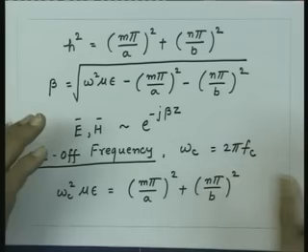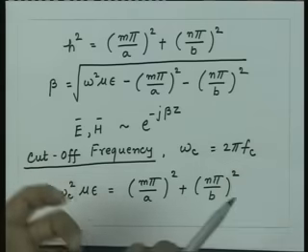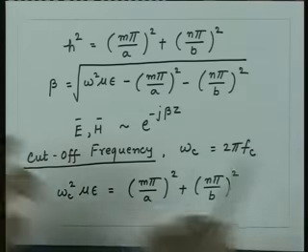Now if you want to send information on this waveguide, we will put the energy inside this waveguiding structure, and if a large number of modes can be supported, if the waveguide does not have single mode operation, the energy will get distributed into various modes, that means various combinations of m and n. Each mode will have its own velocity for travelling. So as they travel, the energy going on different modes essentially separates out. The phase relationship between different modes is broken.